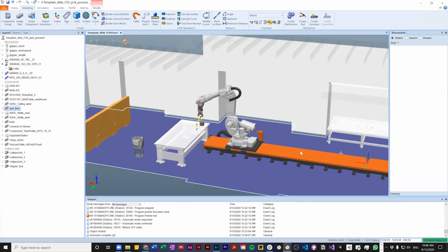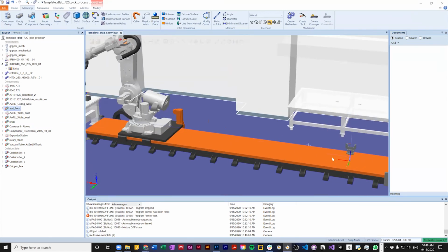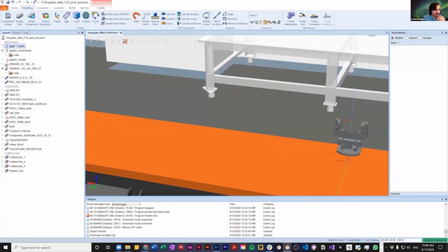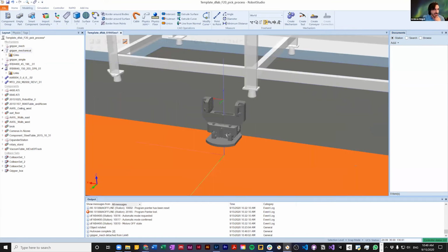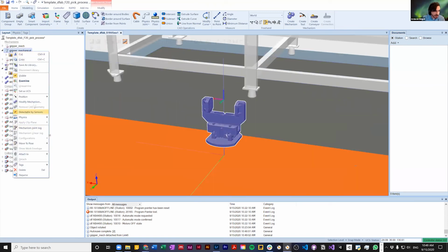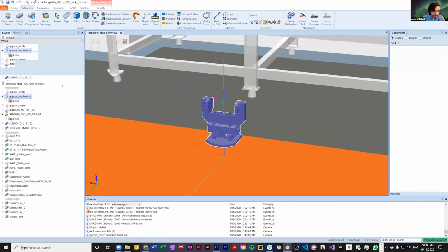Okay, so I haven't installed this tool on my robot. So let me detach this tool, make sure it's not on the robot, and let's hide it so it's not going to make any mess with my other files. As I mentioned, first we need to rotate this tool to get back to that 45-degree rotation. Again, I'm selecting Z because Z is the vertical axis here, and you can see that the blue line is the vertical axis, that's Z.